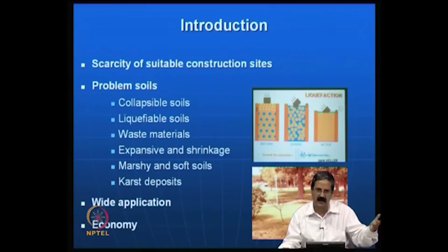The liquid limit, the highest water content, is in the range of about 100%, and the shrinkage limit could be as low as 10%. This extreme range of water contents in expansive soils causes significant expansion and also significant shrinkage, leading to a lot of volume changes, and because of this you have problems like distress in foundations, loss of contact, and many other things.